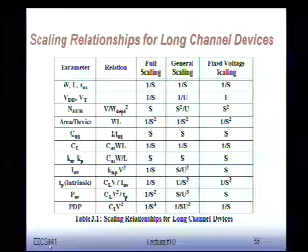It's more complex than that. They have more than one scaling parameter. But think about it, for instance, if I would do full scaling, which means I scale supply voltages in the same way as we scale the dimensions of the technology, we see that the propagation delay goes down with a factor S from generation to generation, just as we have shown happening in reality. Average power per gate goes down as a factor of S squared, and the power delay product, or the energy, goes down with a factor of S to the third.